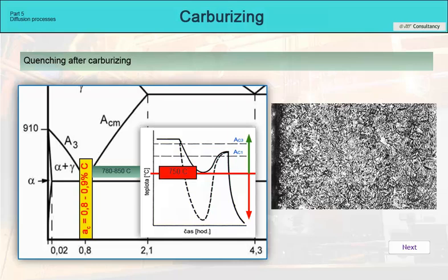However, we cannot do this with a double-sided furnace. The batch must be taken out of the cold chamber, transferred to the other side of the furnace, and reloaded back to the hot chamber. In this case, however, we are already talking about option 4, where we let the batch cool down in a cold chamber below martensite start temperature, usually below 300 degrees Celsius, put it back in the heating chamber and heat it to a quenching temperature according to the saturation of the layer.